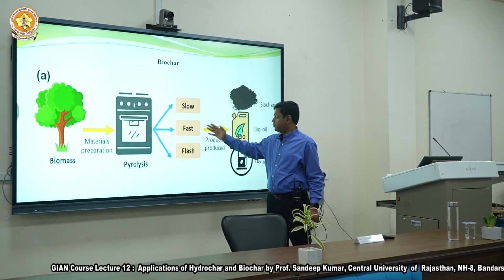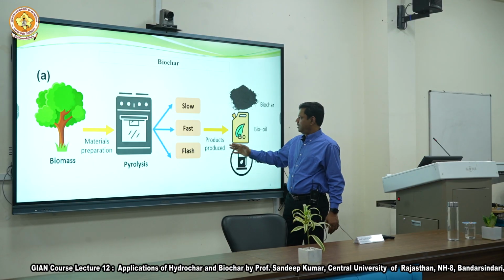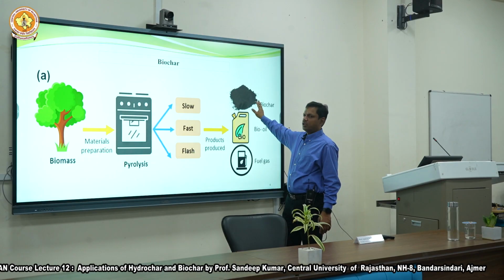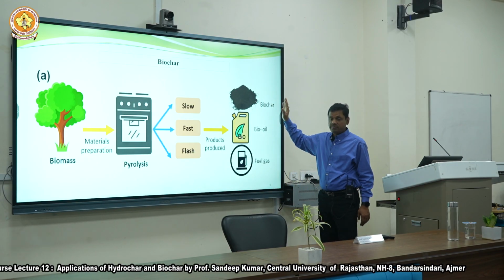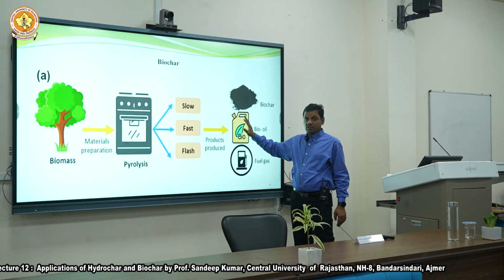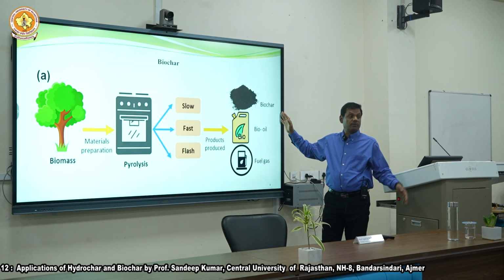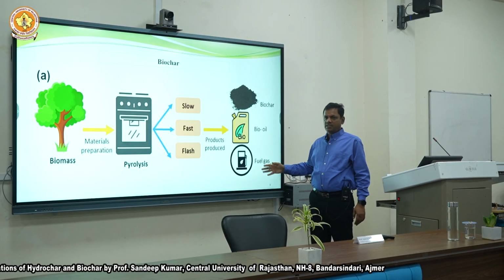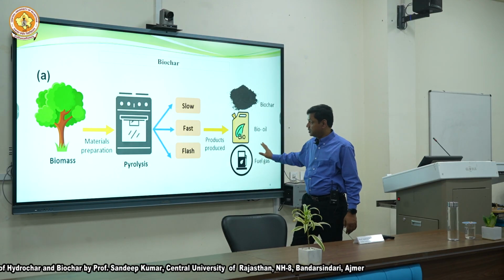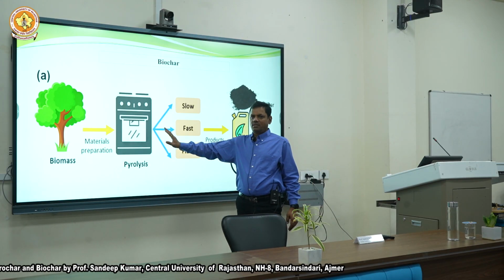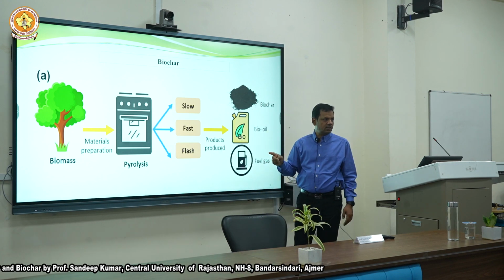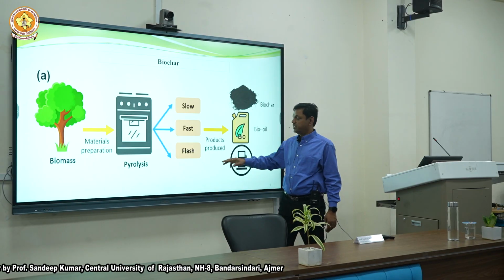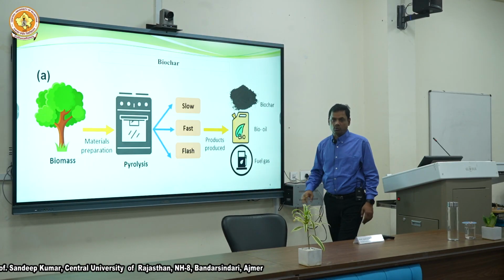And slow pyrolysis, fast pyrolysis, flash pyrolysis. Slow will give you more char, and this is good for soil amendment, filtration application. Fast pyrolysis will give more oil. You will look at economics, do you have enough feedstock to go in the oil direction or not? And some gases definitely. In a pyrolysis unit, typically gas goes back, recycling back to the burner, but still it has calorific value. If you begin recycling, then you get cleaner gas and more CO2.